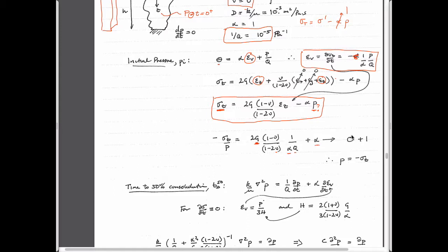It turns out that all of these components in the first term are basically zero, and so when we load it, we expect that it represents this case of a very soft medium where the fluid can't escape from the pore structure quickly, and therefore the initial condition is that the fluid pressure in the medium is exactly the same as the stress that's applied above it.